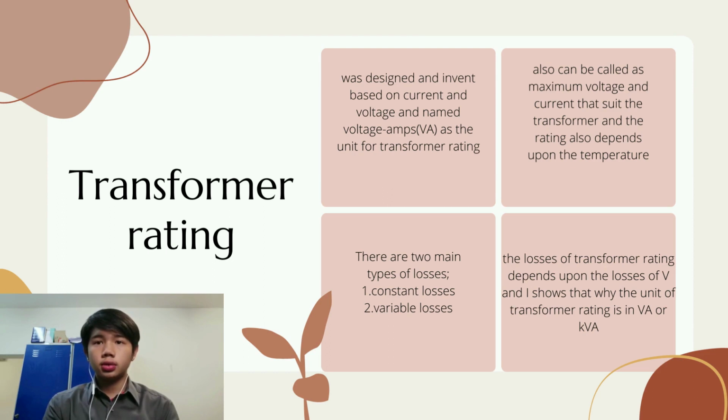It is built for scientists to define the losses of voltage and current. Transformer rating can also be called the maximum voltage and current that suits the transformer. The rating also depends on the temperature rise. If the temperature rises, the rating also decreases. So the greater the effectiveness of cooling of a transformer, the greater the transformer rating.